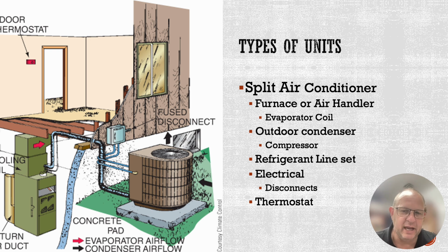The condenser is located outside, remote from the evaporator, which means that we need interconnecting tubings known as refrigeration lines that are supposed to be field installed by a service technician that runs from the condensing unit, maybe through the crawl space, maybe through the attic, into the indoor unit, where we will braze those two pieces of equipment together with those interconnecting tubes so that we can provide cooling for individual houses.